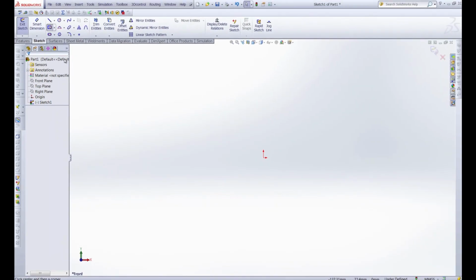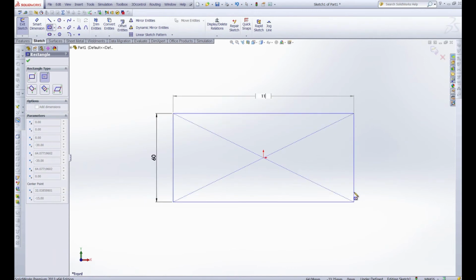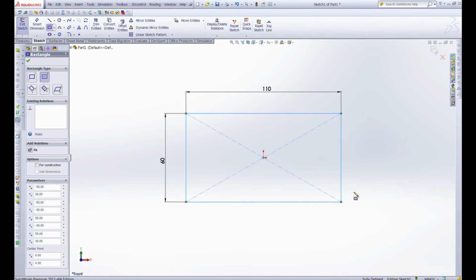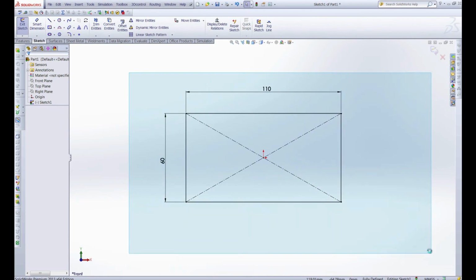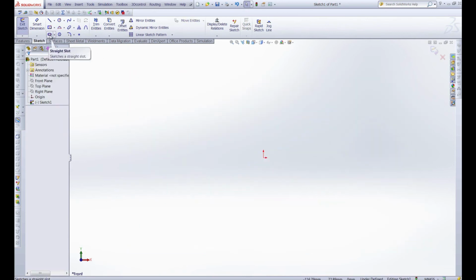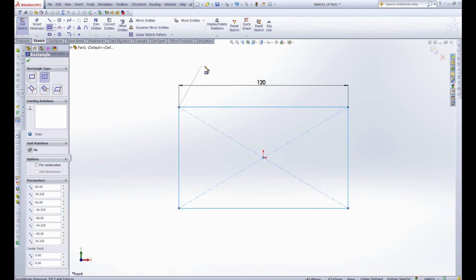Now when we do the same exact thing, you can see that our functionality is the same. We can still type in 60 millimeters, hit enter, type in 110, hit enter, and then we have our box. Now once we close our rectangle or hit escape, you can see that that sketch is fully defined and we have our dimensions created. The same functionality exists if we do want to create that center rectangle again and just dimension the second value. We can hit tab, enter in a dimension, and then hit enter, and now the only side that received that dimension is the one that you specified.